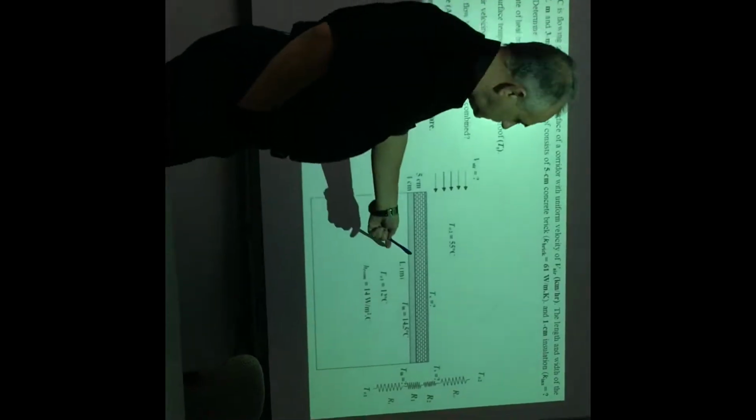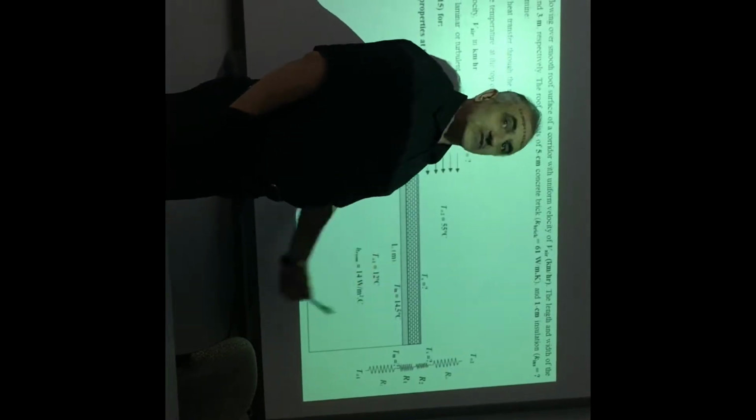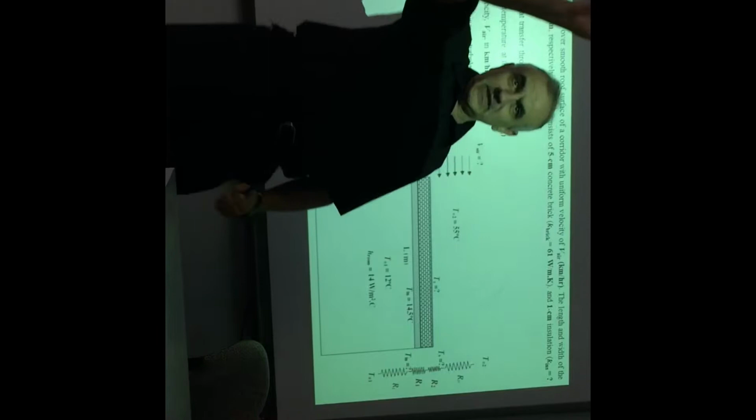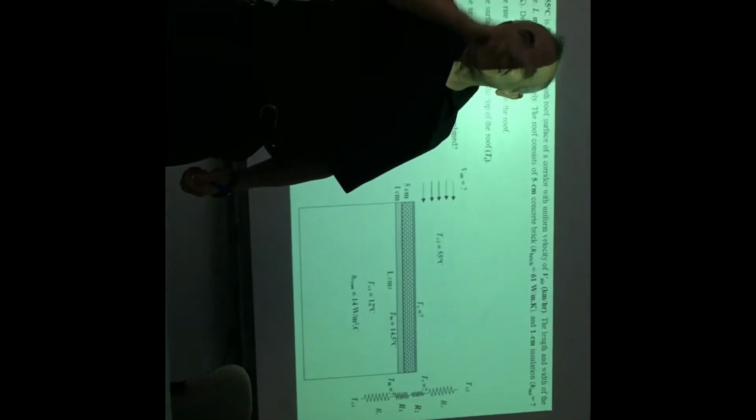Doctor, can I use T for the bottom surface? Yes, what do you mean? Ts minus Tn? Yes, of course. You can use it, because Ts minus Tn has in the denominator only two resistances, the conduction ones.